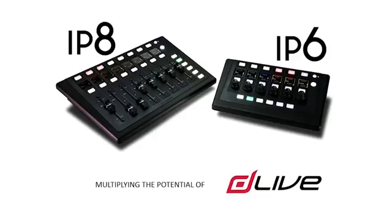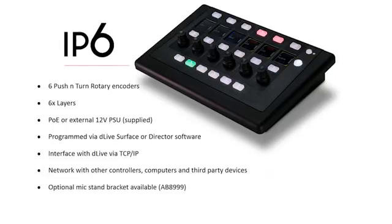installation in a venue. Now, the IP6 comes with 6 push and turn rotary encoders. Push and turn means that they have a dual function. So normally they control, say, the level of a channel, but you can access the pan control by pushing and turning the knob. It can be configured with up to 6 layers. So if you see the row of backlit soft keys on the bottom row, those keys can be configured for layer control, which means that you can control up to 36 individual channels with a single IP6 device.